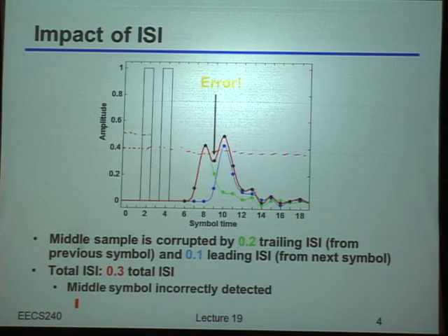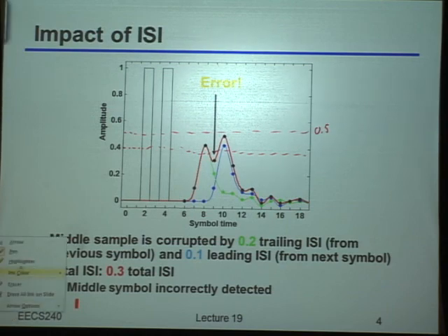So now, if I put it at 0.5, what do I interpret everything as? Yeah, it's all zeros. So now I actually have enough quote-unquote intersymbol interference, meaning the added up weight of all of these secondary kinds of things was big enough that it actually pushed all of my stuff below the threshold. Yes?